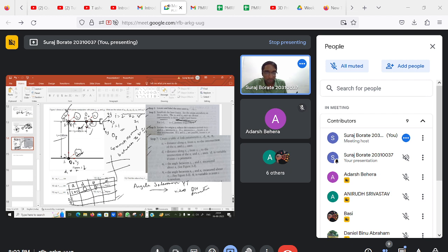So what is alpha? The angle between zi minus 1 and zi. So the angle between z0 and z1, what is the angle between them? 0 about xi, they are obviously parallel. So 0, there is no twist. Okay, there is no twist. So this is 0.